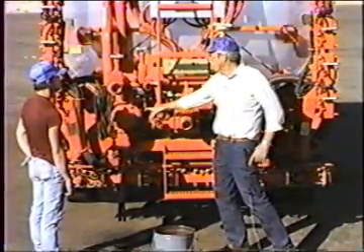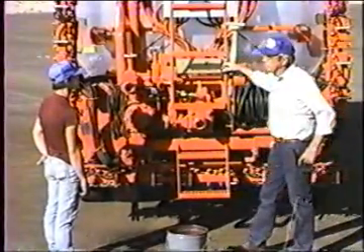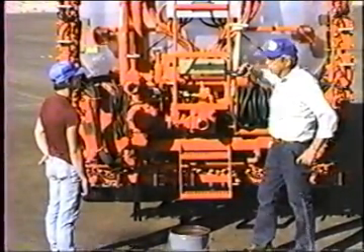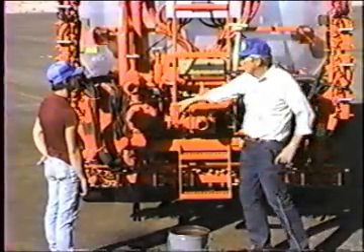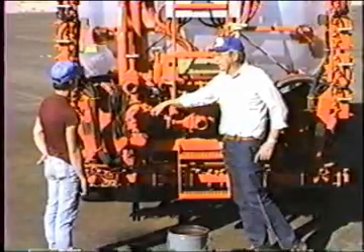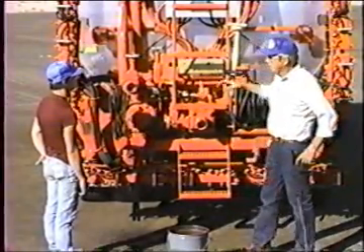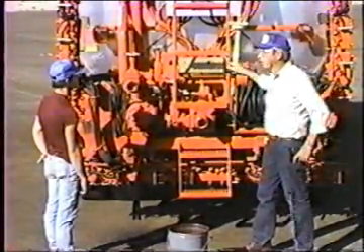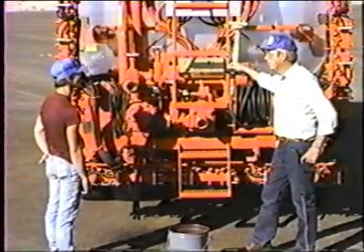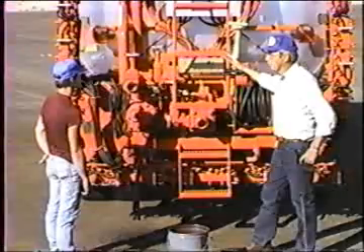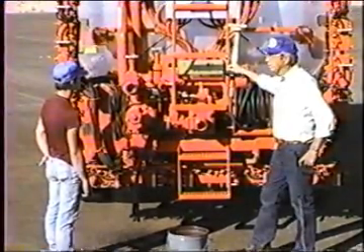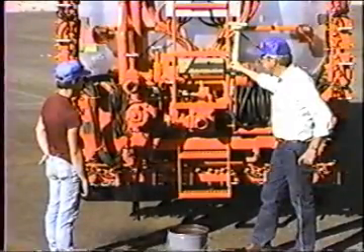It'll finally relieve when the hydraulics see about 5,000 psi of hydraulic pressure trying to turn the pump. But that all converts to about 300 pounds of asphalt pressure. All 300 pounds of asphalt pressure will pop about any hose that we're going to try to pump through. And that makes a terrible mess. As well as it's fairly dangerous because asphalt, and maybe we're pumping 500-degree material, it burns. You know, it French fries you if you get into that.